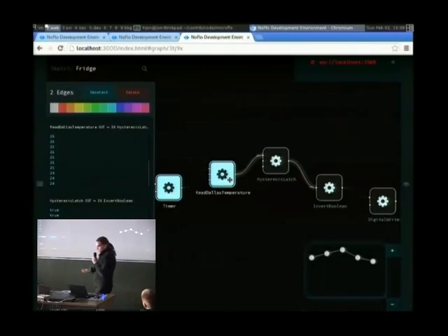It reads the temperature from this digital temperature sensor. It goes through a hysteresis latch so that I can have a different threshold for when to activate the cooler than to drop it, so that if the temperature fluctuates around something, then it won't go on, off, on, off like crazy. And because I wanted the output to be on when it's too cold, I had to put an invert boolean in there. And then I just write that status to the output, which is, in this case, the LED. That would normally be the relay for the output.